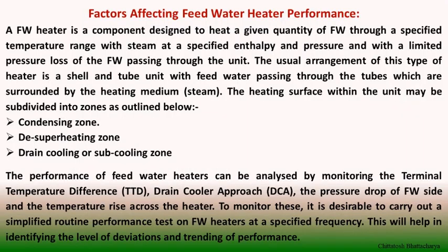So a feed water heater is a component designed to heat a given quantity of feed water through a specified temperature range with steam at a specified enthalpy content and pressure, and with a limited pressure loss of the feed water passing through this heater. The usual arrangement is shell type heaters with a shell and tube arrangement, where feed water passes through the tubes and the heating medium passes surrounding the tubes.